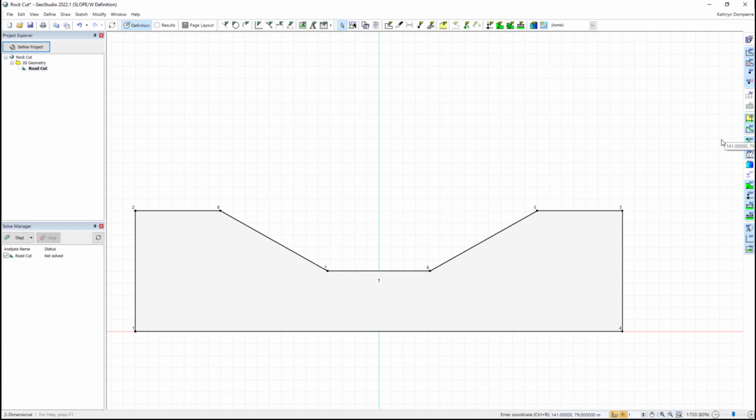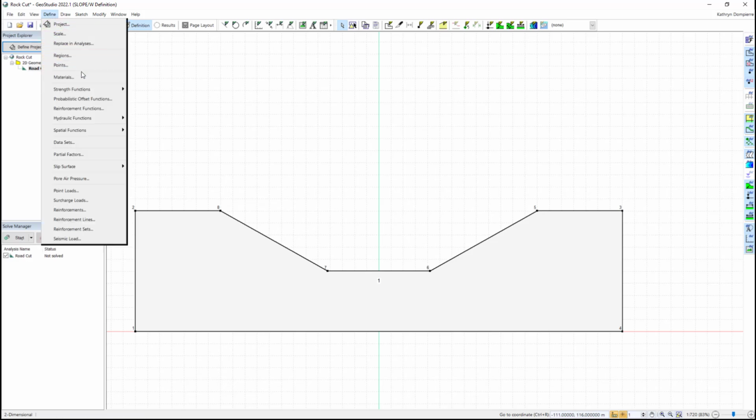If I were to perform a stability analysis on a rock mass using this symmetrical domain, I would normally obtain identical results, no matter which side of the rock cut I choose to analyze. But what if my rock mass actually features two joint sets? We should probably expect that the side of the rock cut, which is preferentially aligned with the most joint sets, should show a lower factor of safety. Let's verify this using the compound strength model.